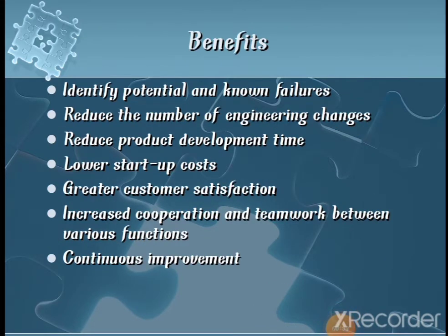Next, what are the benefits of FMEA? It identifies the potential and known failures. We can study what problems can come further. It also assists in selecting design alternatives.